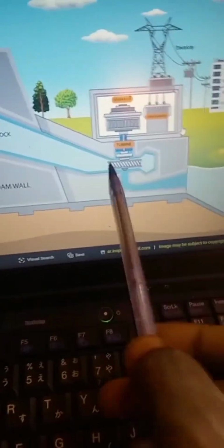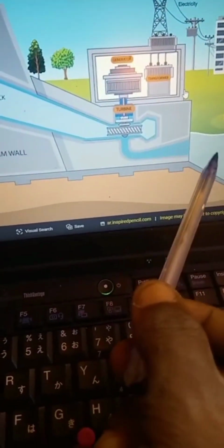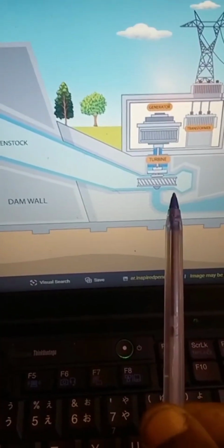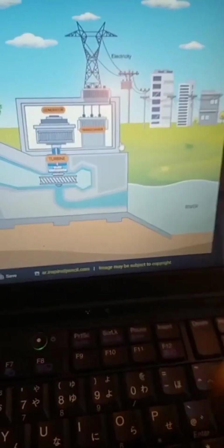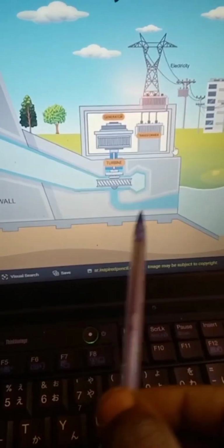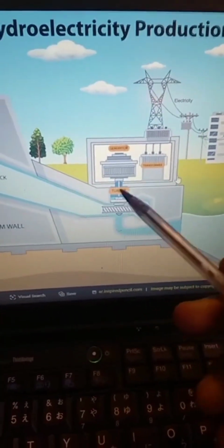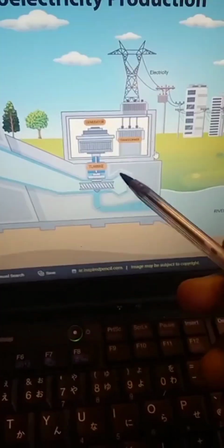The other thing is the flow back of water. Remember, this water should come, get in here, rotate our turbine, then get back to the river and continue flowing. So this outlet here is very important to consider. So we can put our point number 5 as outlet diameter. If you build a very thin diameter here, this water can accumulate and overflow in your generation station powerhouse.